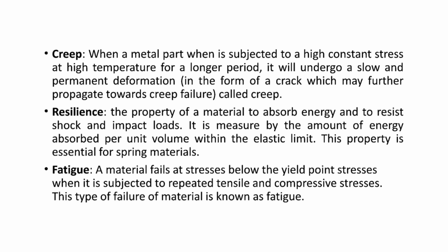Resilience. This is the property of a material to absorb energy and to resist shock and impact loads. It's measured by the amount of energy absorbed per unit volume within the elastic limit. This property is absolutely essential for spring materials. Fatigue. A material can fail at stresses below the yield point when it is subjected to repeated cycles of tensile and compressive stresses. Think of bending a paperclip back and forth until it breaks. This type of failure is known as fatigue.